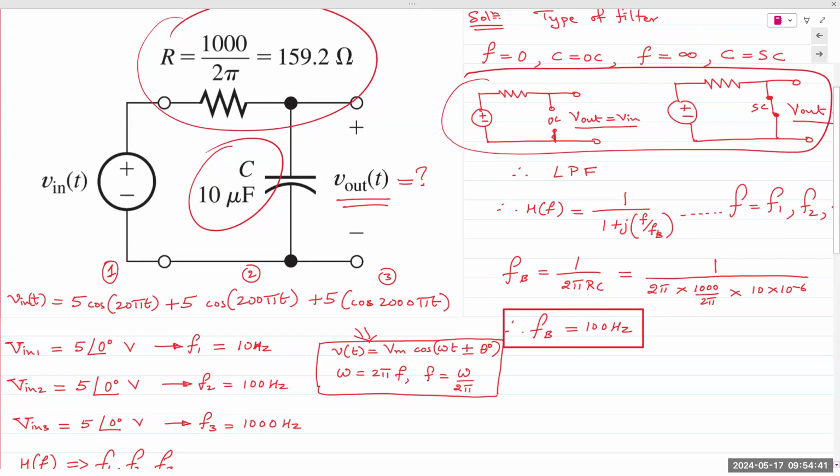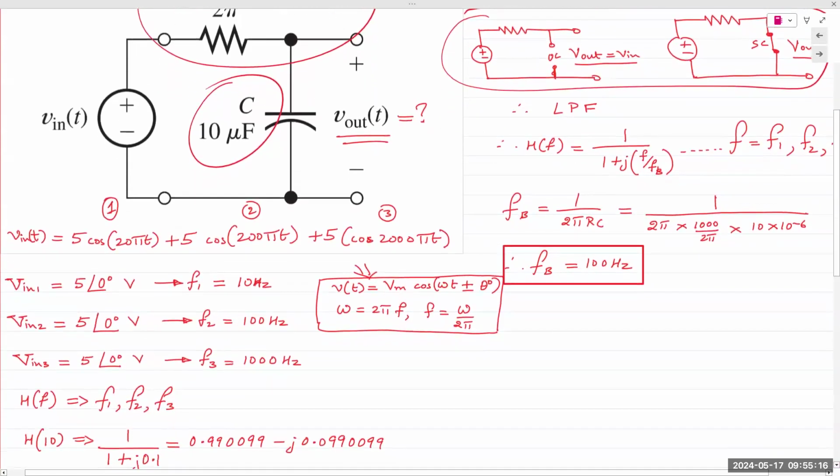So if you look at these 3 components, they all have the same magnitude, 5. Plus, they also have the same angle, 0 degrees. So phasors for all 3 components are exactly the same, because phasors do not have any frequency information. Even though the frequencies are different, the phasors are exactly the same. But that doesn't affect how our circuit or our analysis works. We simply compare it to the standard expression and extract information about the peak values, about omega, and about the phase angle theta.